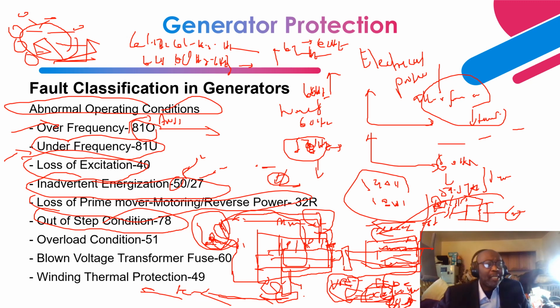So if for whatever reason now, one of them should lose synchronism, right, that needs to be detected and for this generator to be isolated as quickly as possible, because other than that, this is going to cascade to the other generators and they will all lose synchronicity.